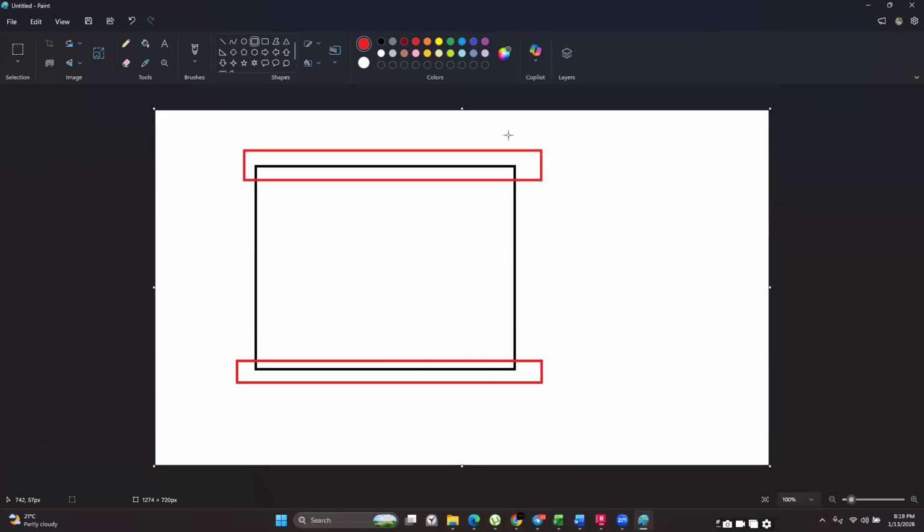But in real life, we are going to be providing beams at these edges. Okay, we are going to be providing beams at these edges, and what these beams do is that they prevent this slab from being uplifted at the edges. And if these slabs are being prevented from rotating at the edges, we are forcing it to have a lesser amount of degrees of freedom here. We are restraining it from basically deflecting upwards.